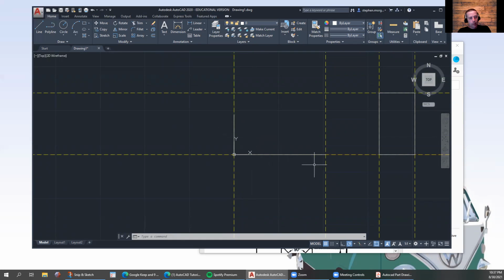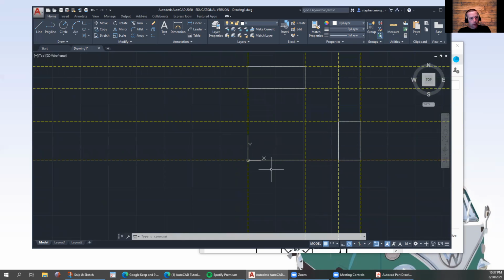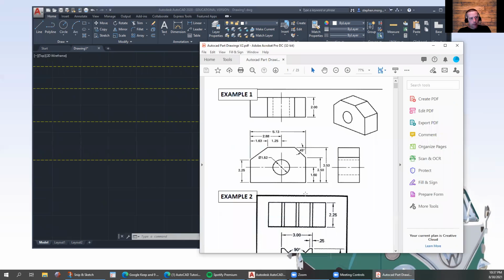Instead of snapping between 2 points, we can just type in a distance and get your cursor going the correct direction and you're good to go. Let's see. Okay. So let's maximize this. Next, I'm going to draw this line going vertically, and that's 2.5.